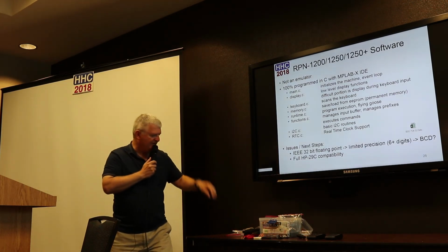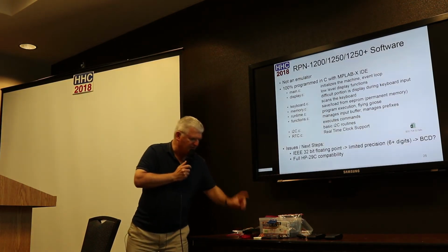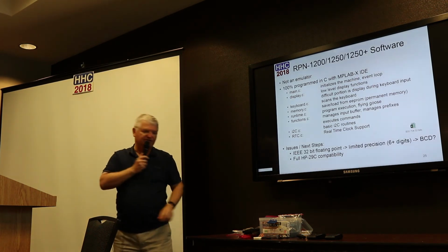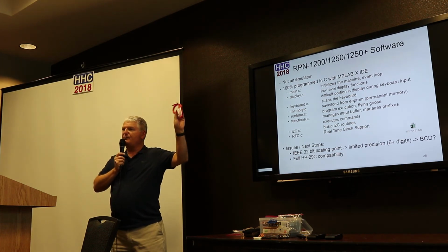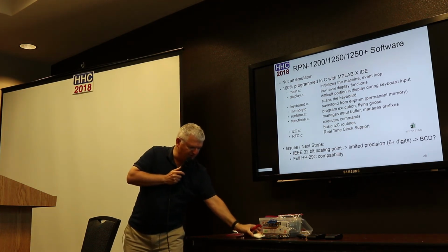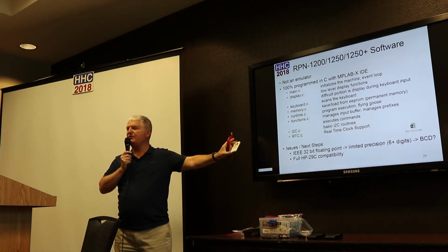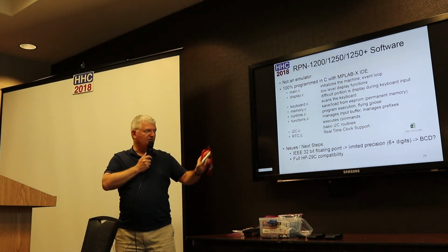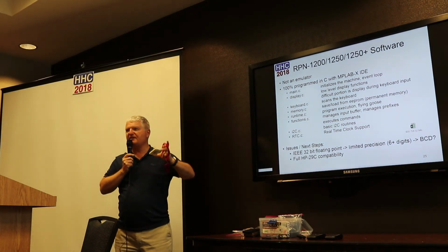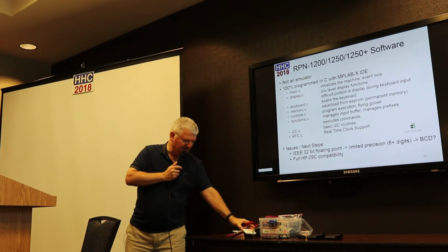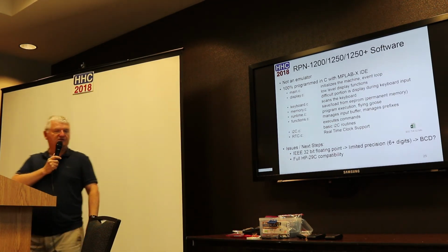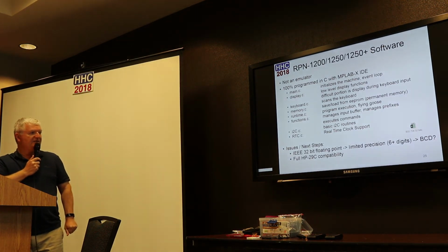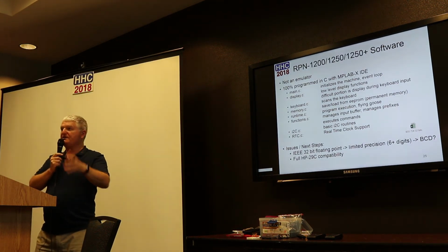One more thing I wanted to mention. The chip that you see on the board for the 1250 is programmed with a simple flash programmer. I have a small breadboard where I put the chip, program it, and then put it in the machine. I don't have inline programming yet. I guess that's the next PCB, but it's very, very easy. The development system is very good, so it's very easy to use.